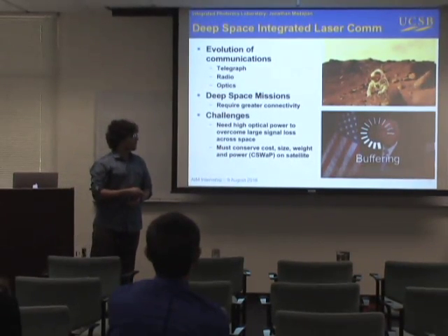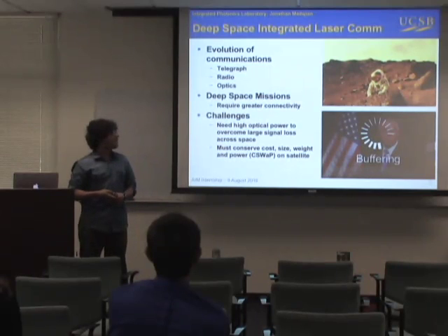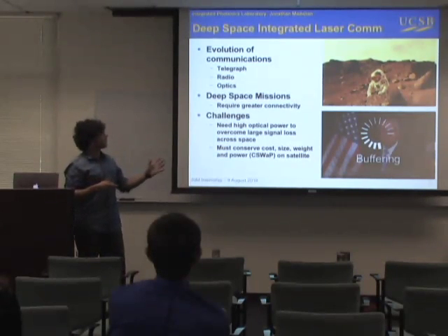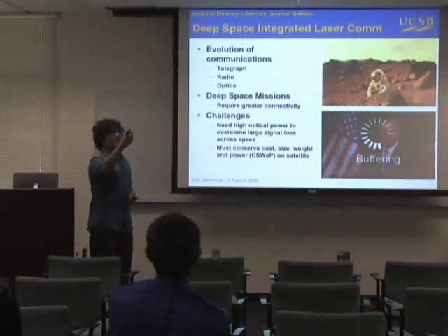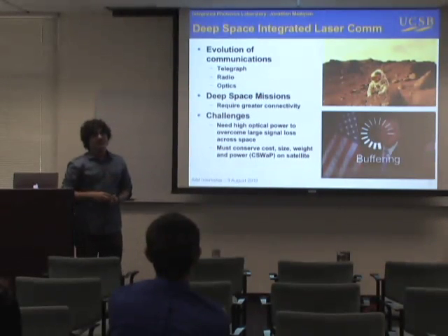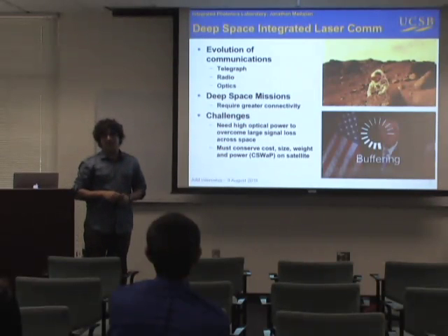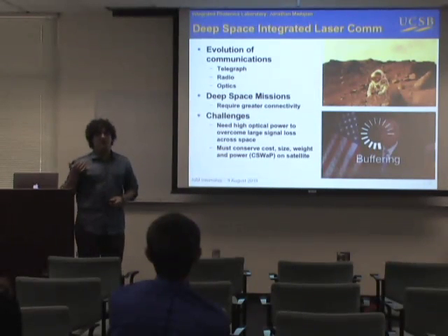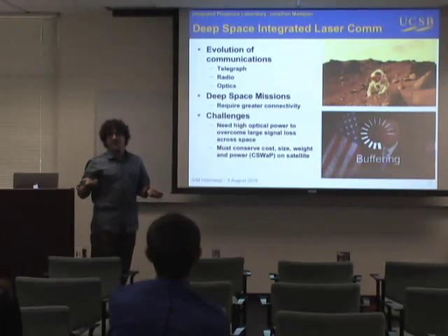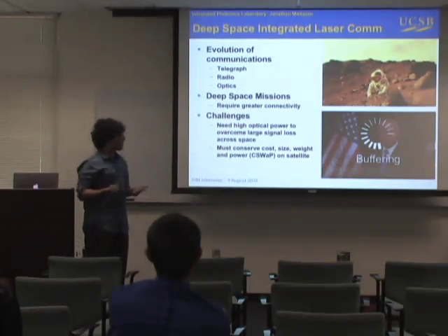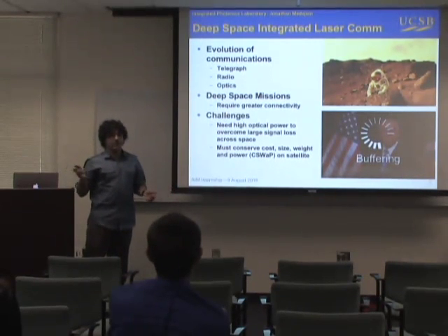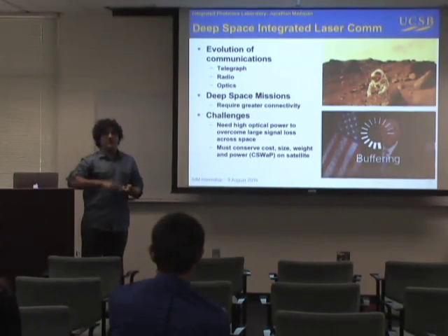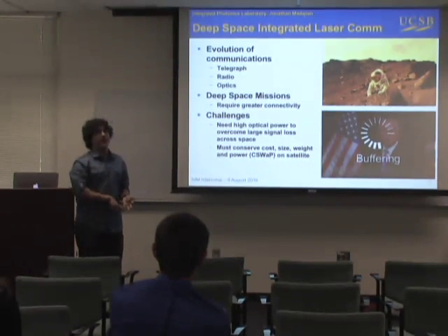However, there are issues with laser communication. One you may notice with optics is that this screen has been waving for the past couple of presentations. That's due to atmospheric interference between just the projector and the screen. Now, if you can imagine going from Earth to space, those disturbances can be gigantic, and we need to find ways to overcome them. There are also large signal losses over the vast distances in space, but if we can integrate these optical systems, we'll be able to reduce the cost, size, weight, and power of these subsystems.